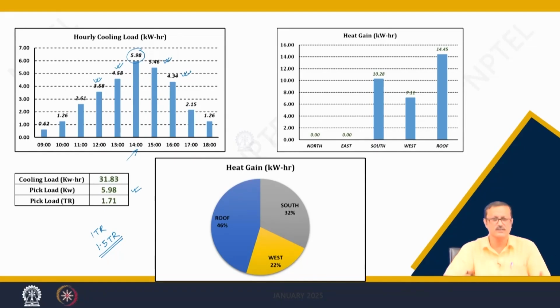It will be a little bit higher, maybe 26 or 27 degrees, because your total demand is almost 1.7, but the machine can give an output of only 1.5. Of course, there are a lot of other things also, like the efficiency of the machine, but let us assume efficiency is 100%. Even in that case, a 1.5 tonnage air conditioning unit will not provide you the best efficient cooling if you put your set point temperature at 24 degrees, right.